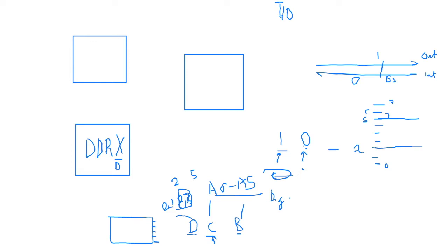We said pin 2 is a push button switch. So you have a push button switch on there, or a switch that you press to close. Now this switch is an input, so because pin 2 is an input, we want to set pin 2 to a 0 from the beginning. So you can write something like this: pin 2 as an input, and in order to configure it as an input in the data direction register, you expect pin 2 to be 0.